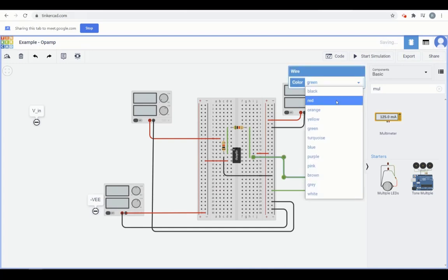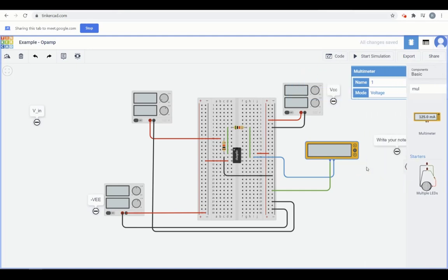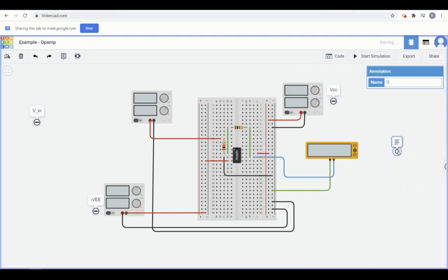There is nothing wrong in what we have drawn earlier, but we could not observe inversion there because the oscilloscope does not have those features. The oscilloscope in Tinkercad is a very basic oscilloscope. You do not have a trigger value, you do not have a zero instant, which is why I'm now saying, let us do it in DC and see whether what we've done is correct or not.